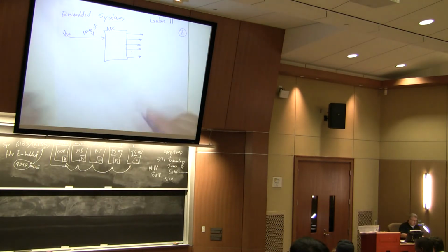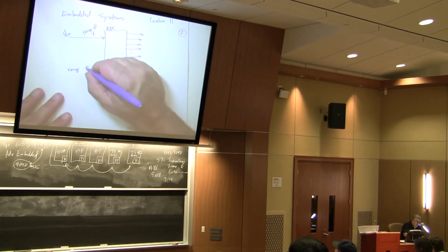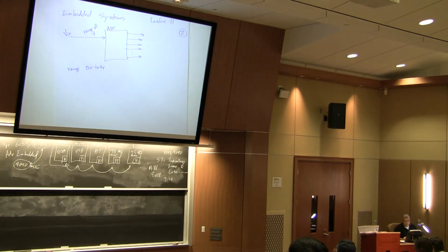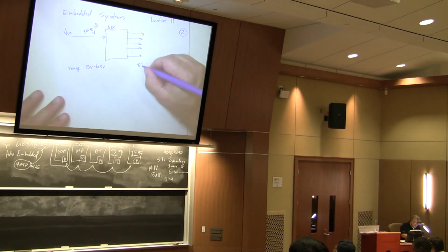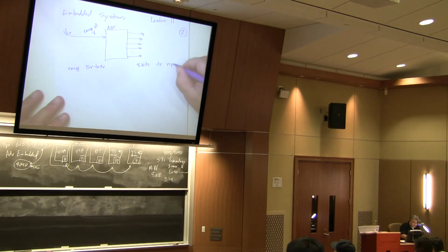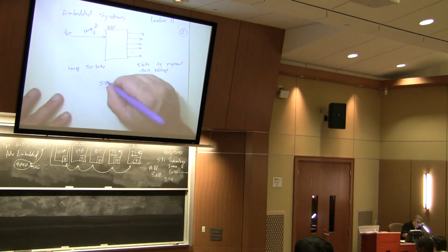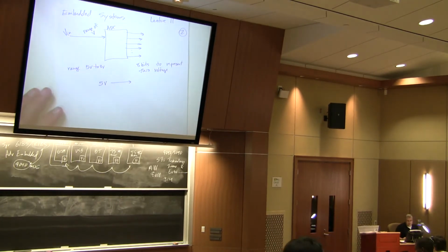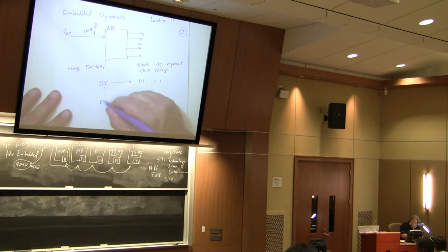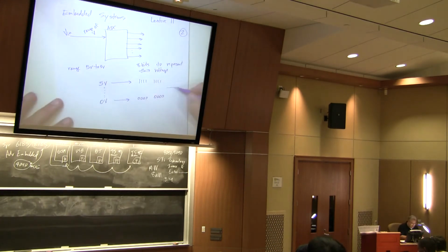As an example, let's say our range of voltages is going to be 5 volts to 0 volts. And let's say we have 8 bits to represent this voltage. We've already seen a problem like this in an earlier chapter. I just glossed over it really quickly. So what we're saying is that when you have the value 5 volts, it's going to be the biggest 8-bit number possible, 1111 1111. And it's going to go all the way down to 0 volts, which is going to be 0000 0000. And where it ends up in the middle is going to be due to each of the individual steps.